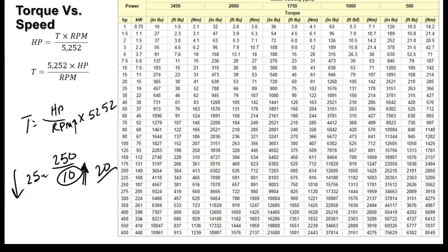So if speed goes up, torque's got to do what? Got to go down. If speed goes down, torque's got to do what? Go up. So we're going to use gears as a torque multiplier. But if I increase the torque on the output, the speed has got to go down. Y'all understand that? Does that make sense? If the speed goes up, the torque's got to do what?